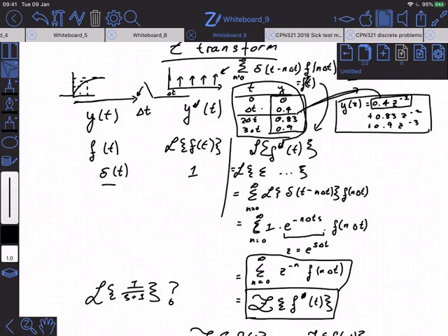And so we're doing a trick here, which I want you to understand, is that all of this working over here is kind of just the mathematical sleight of hand that we use to encode these sampled signals within the Laplace domain. And when we do that, because of all these deltas being shifted, we end up with a lot of these exponential terms, right? Because moving a time signal up by a certain amount corresponds to multiplying in the Laplace domain by this exponential. And we came across that many times when we were thinking about dead time.